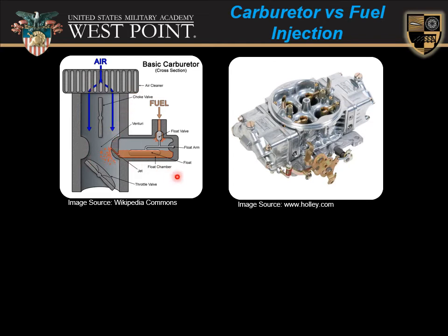Conservation of mass is going to tell me that the air must accelerate. As the air accelerates, it decreases the static pressure. That static pressure creates a pressure imbalance, or essentially a vacuum, that draws fuel out of the float chamber.